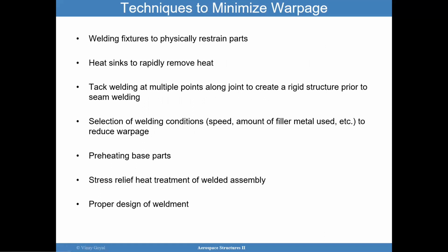There are techniques to minimize warpage: welding fixtures to physically restrain the parts, heat sinks to rapidly remove heat so that you don't get the residual stresses that could start moving the part, tack welding at multiple points to create a rigid structure prior to actually welding, selection of welding conditions such as speed and amount of filler metal used to reduce warpage, and then preheating the base parts, stress relief heat treatment of welded assemblies, and proper design of weldments.